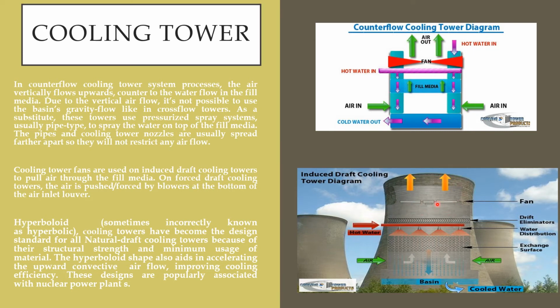This is the induced draft fan, drift eliminators, the distributor nozzle. Hot water is distributed through this nozzle from the top, to the cooling water basin, and cold water. Drift eliminators are provided here to reduce the loss of water and emission while it is distributed from the top. Water droplets should not escape through the induced draft, though we still lose some water.